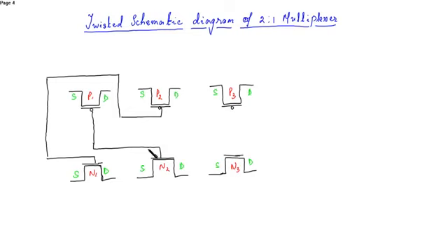So the two gates are connected. Now the source of PMOS and NMOS of a transmission gate are connected. The drains are also connected. So connect from here to here and connect from here to here. Similarly, this is also the transmission gate.